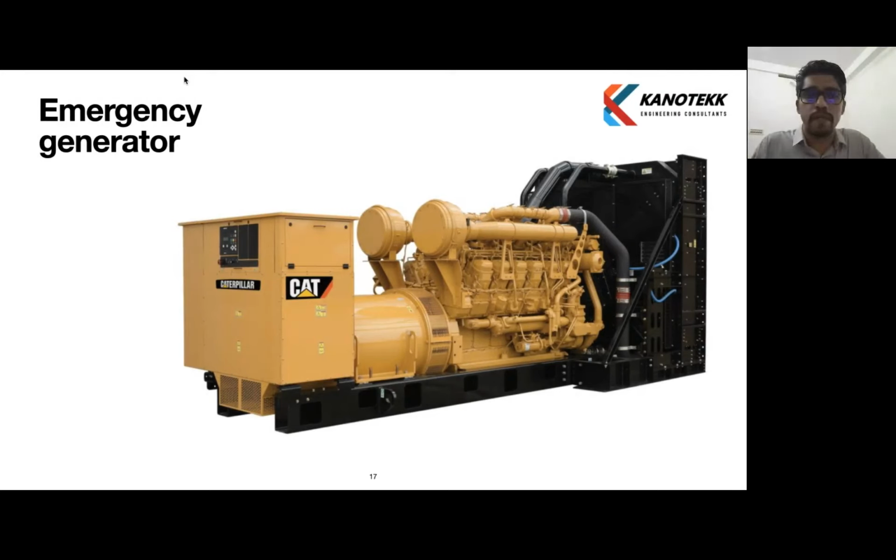So this is a picture of an emergency generator. This will be kept in a separate emergency generator room. As we described earlier, usually the requirement varies from 900 kilowatt to 1100 kilowatt, depending on the emergency generator load calculation. There will be a load analysis which will be done for the emergency generator.